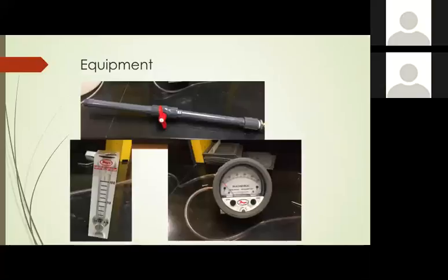So here's the equipment we used. This is a piece of PVC pipe. We put a PVC ball valve in it. It's just an open piece of pipe. It's got a couple of measurement ports right there and there where we can measure pressure. We measure pressure because the pressure drop is really small. We used a very sensitive pressure gauge. The units here, that's 1/10 of an inch of water column. In other words, it is the weight of a water column that's 1/10 of an inch high. That's a very, very tiny amount of pressure difference. These two hoses go out from the two measurement ports and go to the two ports on either side of the valve so that we can measure the pressure drop across the valve.